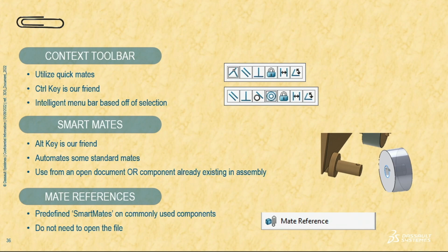There are ways you can do that with naming them, snapping into other components, but what that was doing is almost the same thing as the smart mates, just not having the file open. It was just built in, so it just knew. With the smart mates, we just grabbed an edge and it's looking for that edge to mate to. Here we're defining it in the part, so it's looking for that to mate to. But for instance, if you have 100 parts that look the same